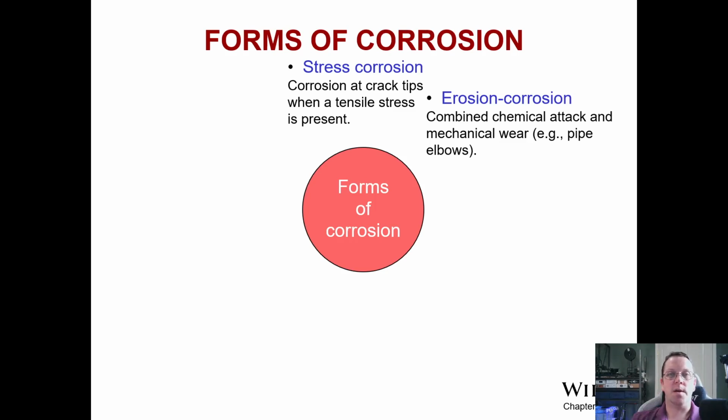things happening there. Think of the kinetic energy of each individual molecule passing by and pounding into the sidewall of the elbow over the course of gazillions of gallons of fluid flow. That's going to create erosion no matter how resistant your material might be. It's going to just mechanically wear out.